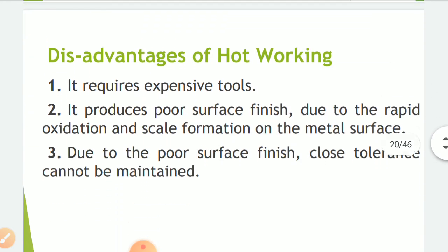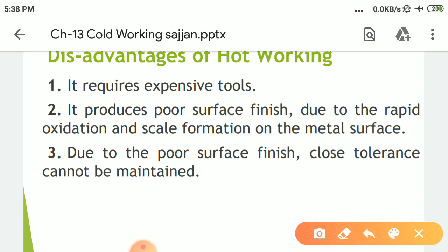Now if we come to the disadvantages part, the first disadvantage is it requires expensive tools that can bear high temperature. It produces poor surface finish. Remember this point, this is very important. Surface finish is poor due to the rapid oxidation and scale formation.